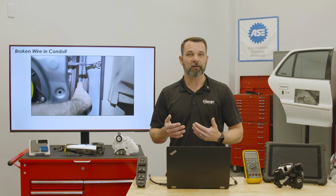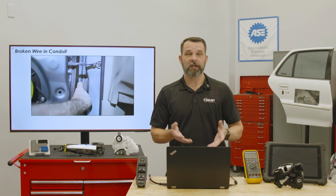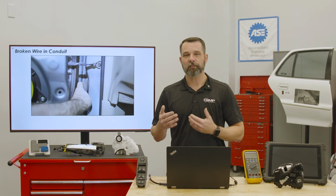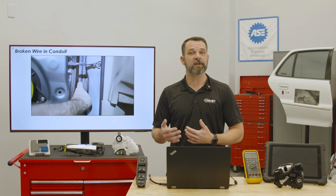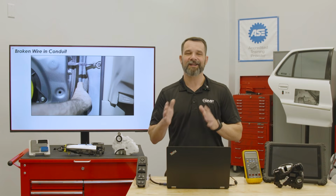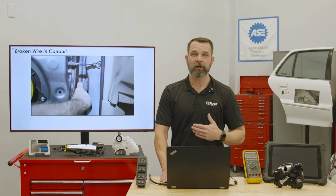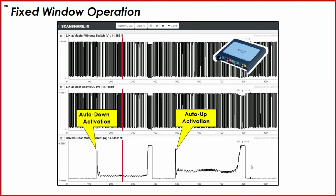With a simple wiring repair, this problem was fixed and the customer concerns were resolved without even the need for an actual part replacement. And now here's a tip for those vehicles you do have a problem finding good information for: save your data. The technician here, after the repair, scoped the signals one last time, not only to verify, but to document the repair and then have a good known capture of the system working properly for future reference if he had something like this come up again.